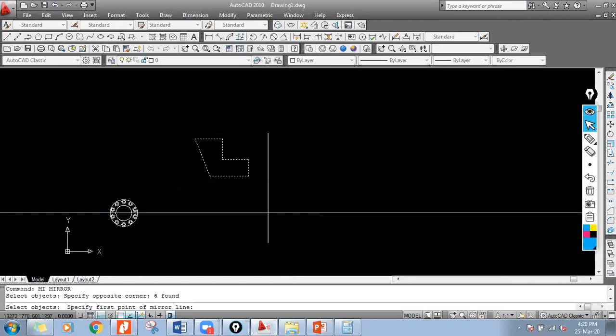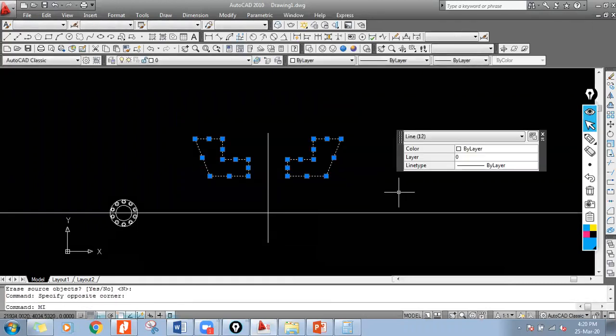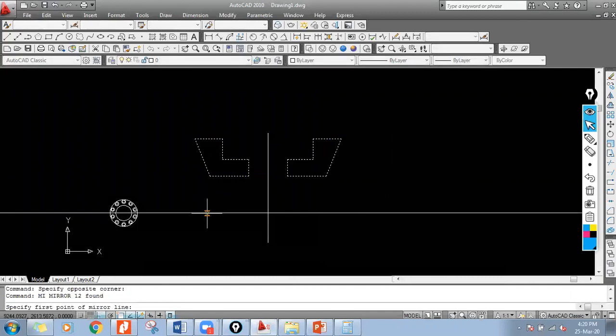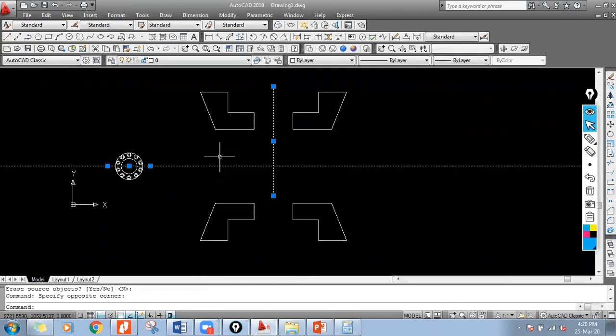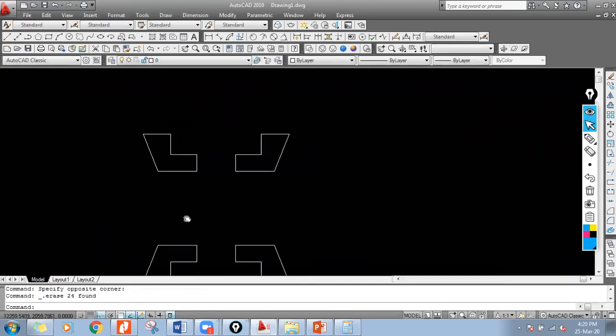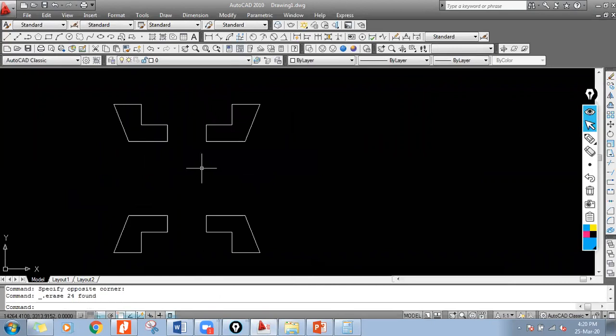Then this is your MI. Enter this and select this. So this is the mirror, right? Select this object, MI. This is the shortcut key for mirror, right? Enter. So this is the mirror. Are you able to understand what the application of mirror is? Yes, sir. Correct?